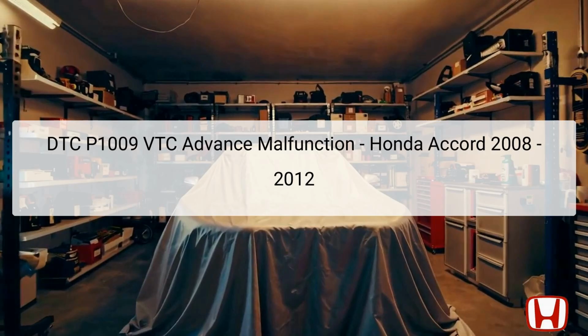These components are crucial for the accurate operation of the engine's valve train, which ultimately impacts the vehicle's performance. The VTC strainer is specifically located within the engine and ensures that clean oil reaches the VTC system. When diagnosing this code, it's essential to collect all relevant diagnostic information, including freeze frame data and snapshots, since these can provide crucial insights into the malfunction at the time it occurred.